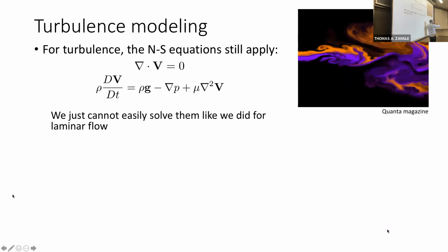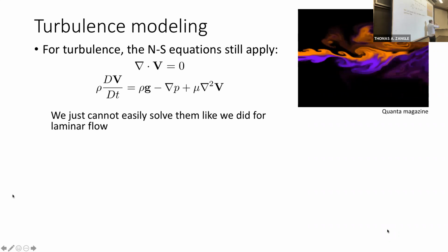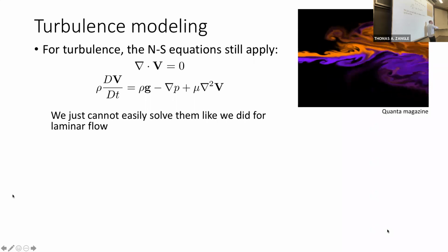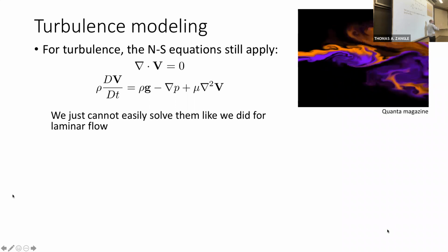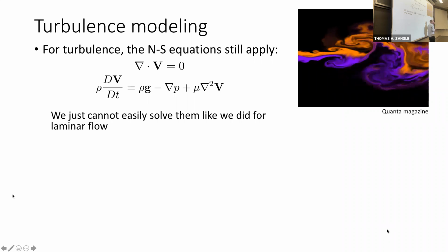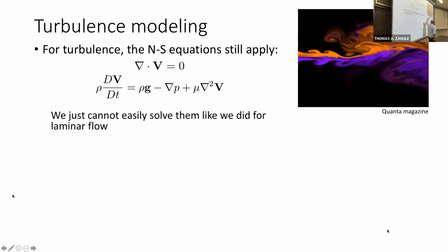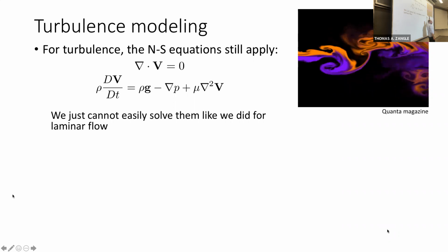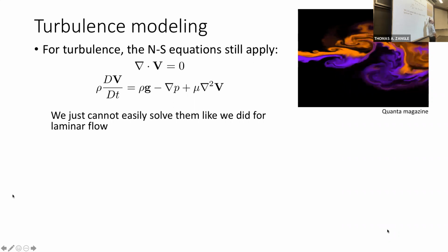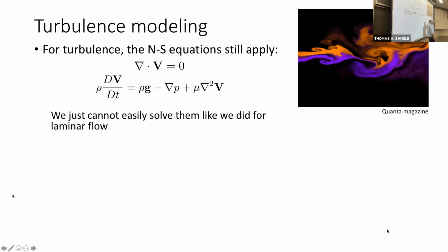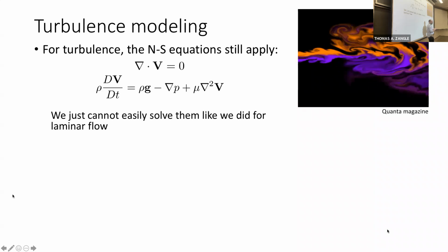And those vortices are creating velocities, not only in the primary direction, right? In this case, down the board that we're concerned with, but also in, let's say, the z direction, moving up and down. And if we were to look at this, this is actually going to end up as a 3-dimensional flow. It's also creating eddies in the direction into and out of the board, which we just can't visualize here. One of the fundamental problems here is that turbulence can create velocity fluctuations. Even though we have a primary flow in one direction, turbulence will create velocity fluctuations, gradients in velocity in all 3 spatial dimensions that vary in time. So it's not even strictly steady.